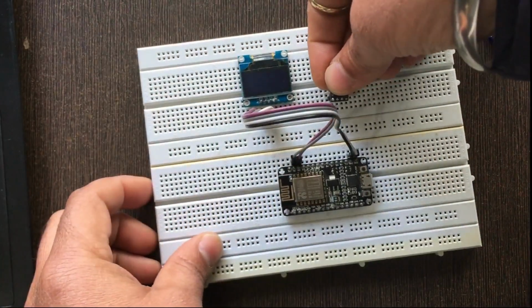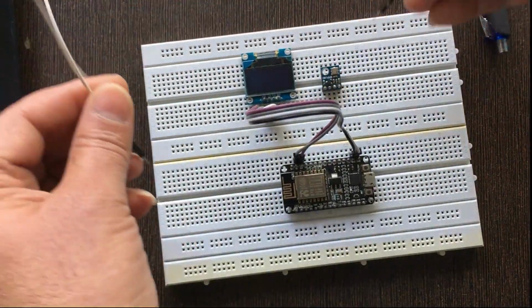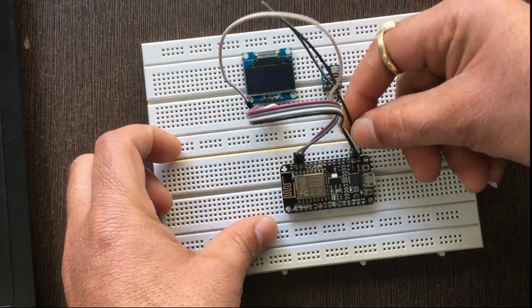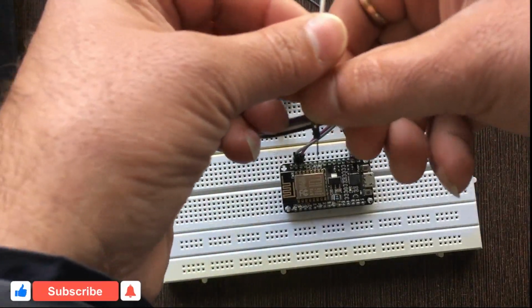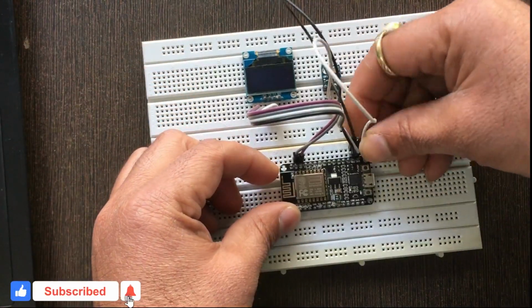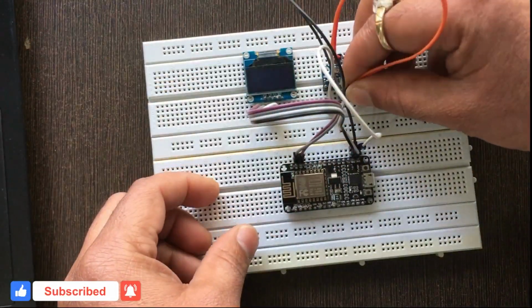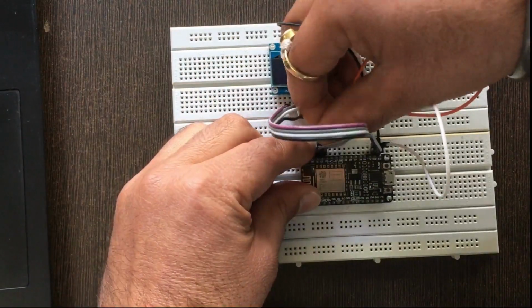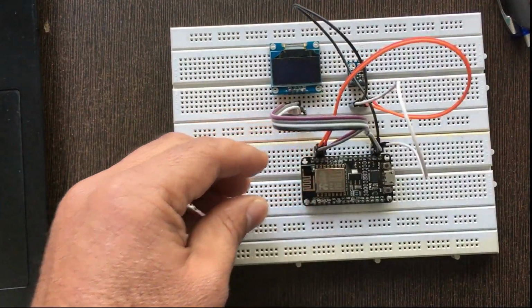Now place the BMP sensor on the breadboard. Take 4 more male-to-male wires. Connect VCC and ground pin of the BMP180 sensor to 3.3 volt and ground pin of NodeMCU. Connect SDA and SCL pin of BMP180 sensor to D2 and D1 pin of NodeMCU.